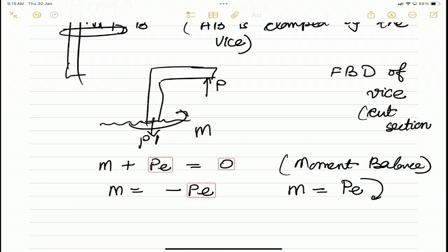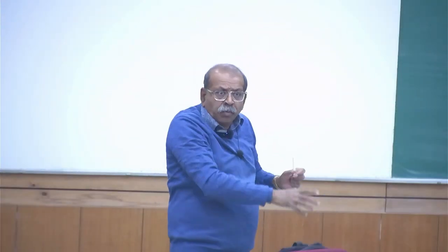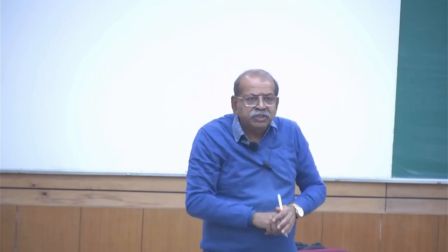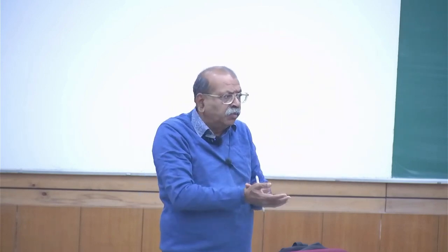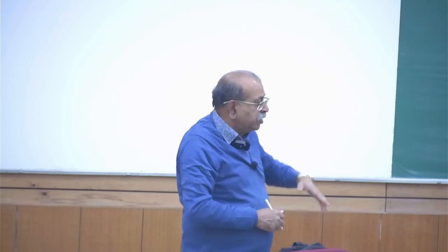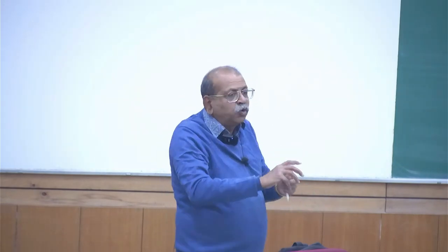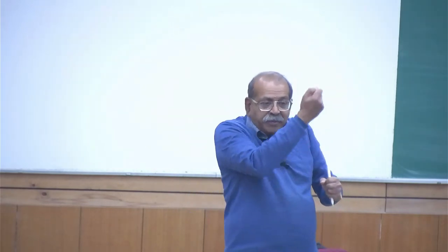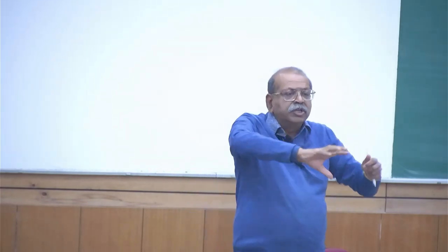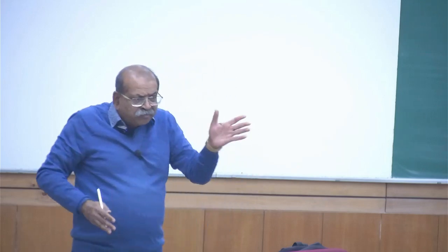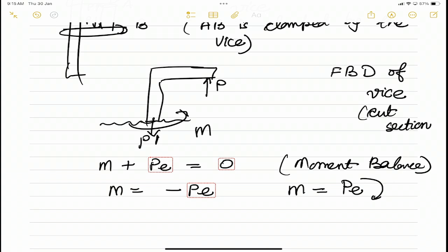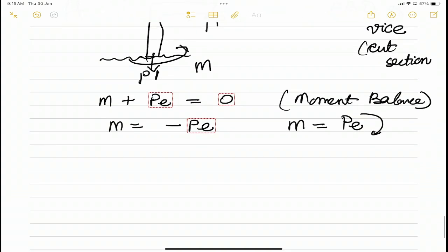So in this rod we will have, in the straight vertical part, a moment along with the axial force which is acting. If I cut any section, I get a moment, which is again a bending moment. So the results which we will get, we can use for this. That means we will have to superpose the deformations due to P and the deformation due to M. We can always do that, provided we are in the linear range and deformations are small. So this is one example where we can extend the pure bending.